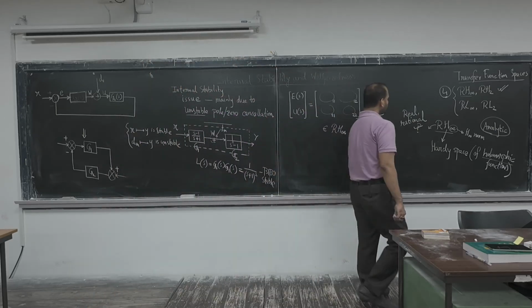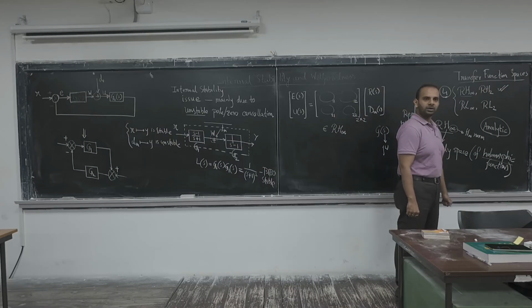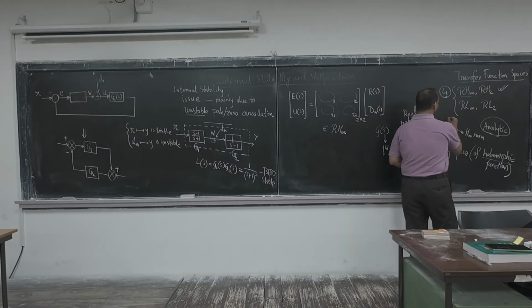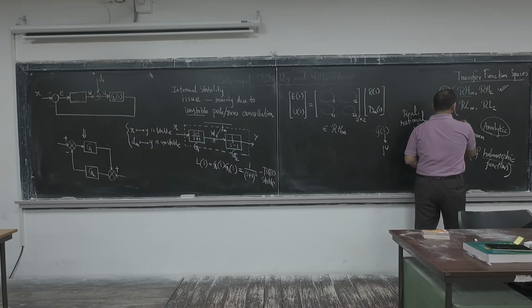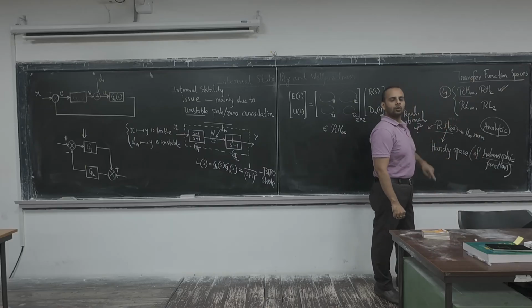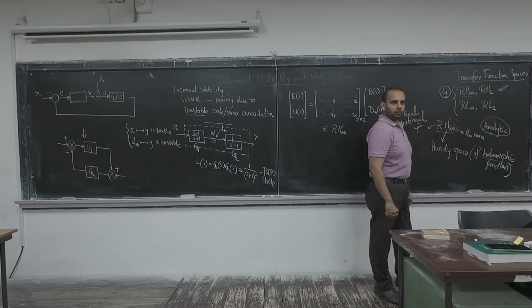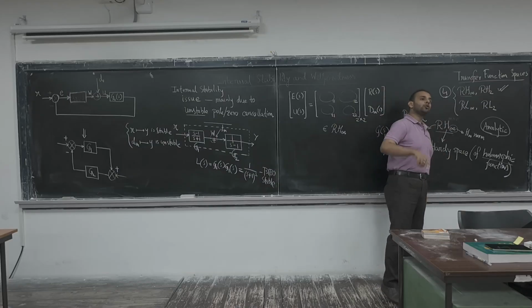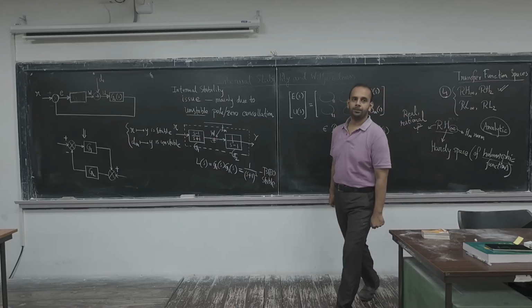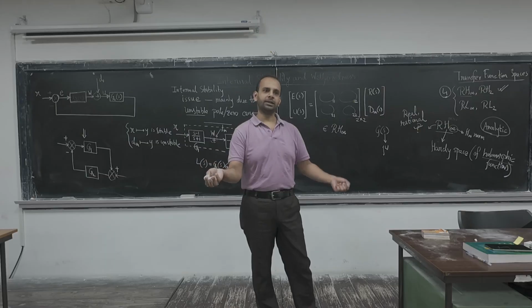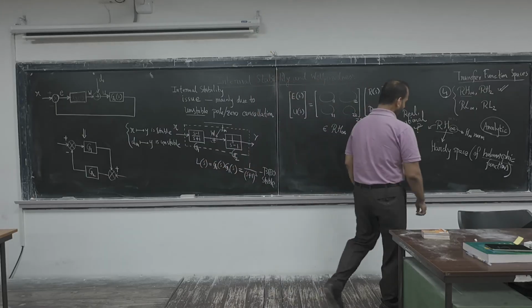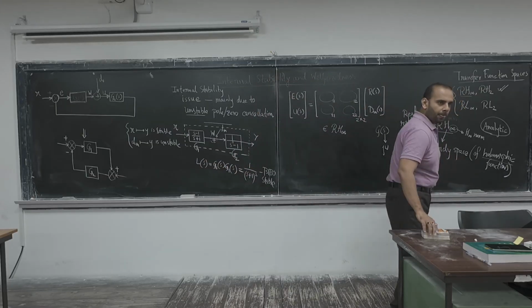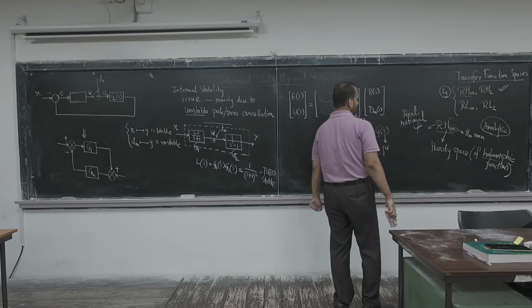Now, of course, it is not only for SISO, it has to be defined for MIMO. Transfer function matrices can be of any dimension: square, flat, or tall. In most cases, the controllers can be unstable. If you have the product of one stable transfer function and one unstable transfer function, then the product will have the same unstable eigenvalue, right? So it doesn't belong to RH infinity. That is the problem.